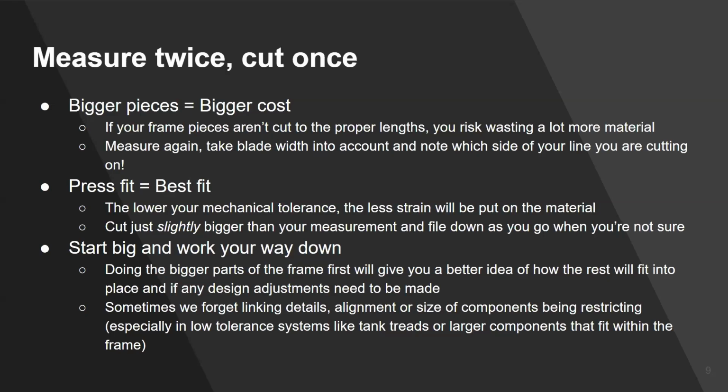So build your frame first. Build your alignments for the bearings that are going to go onto it, then measure out the tread size that you're going to need. Whereas if you do your treads first, then you drill your holes, then you realize, uh-oh, I miscalculated that. Now I'm going to have to go back and recut my treads or remeasure them, or whatever the case may be. So just be careful of those small things.